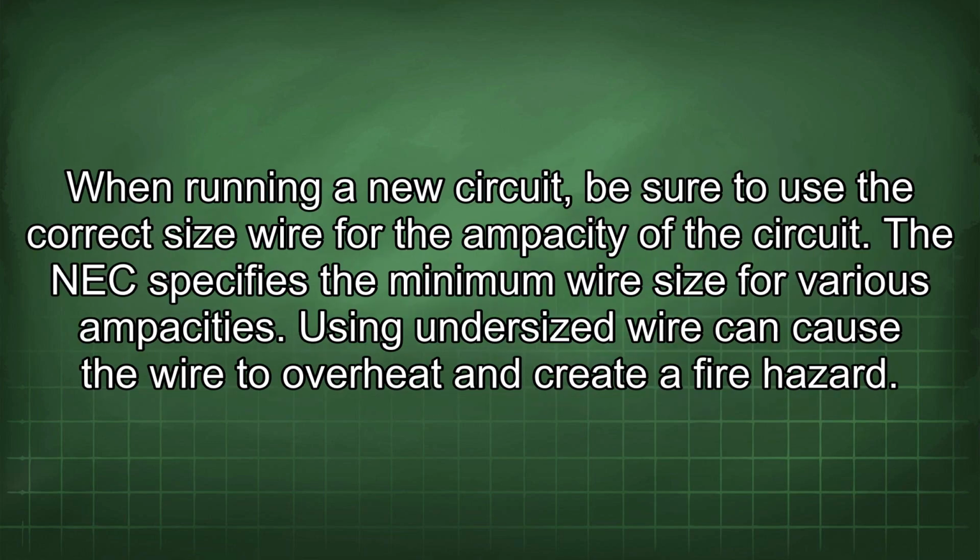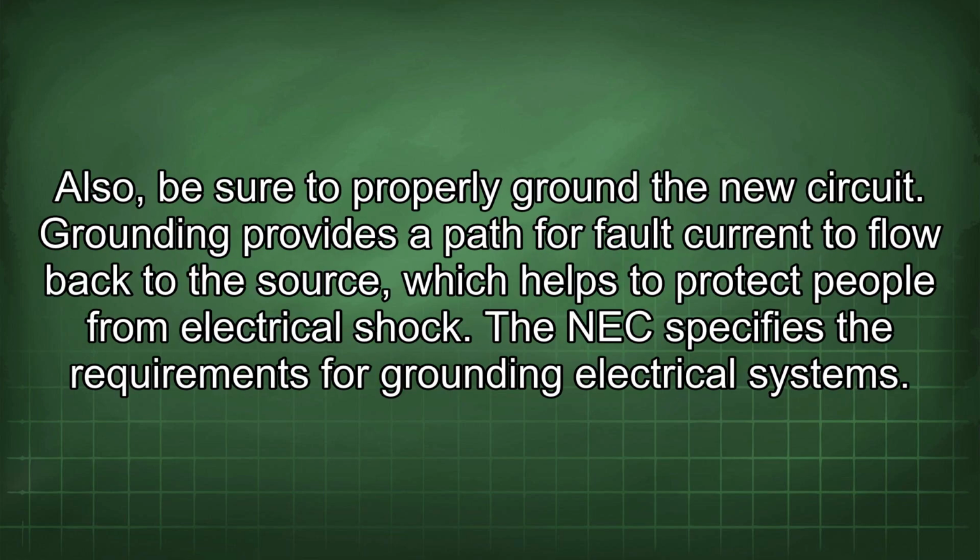When running a new circuit, be sure to use the correct size wire for the ampacity of the circuit. The NEC specifies the minimum wire size for various ampacities. Using undersized wire can cause the wire to overheat and create a fire hazard. Also, be sure to properly ground the new circuit. Grounding provides a path for fault current to flow back to the source, which helps to protect people from electrical shock. The NEC specifies the requirements for grounding electrical systems.